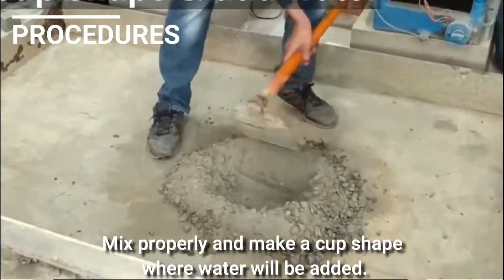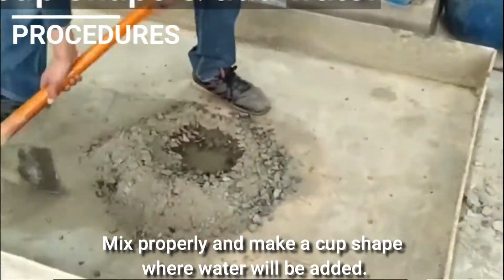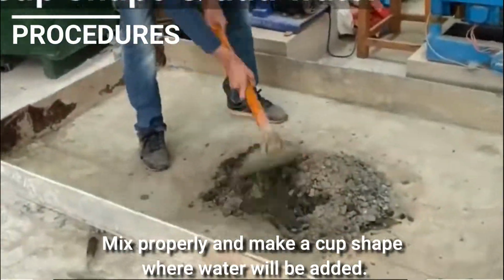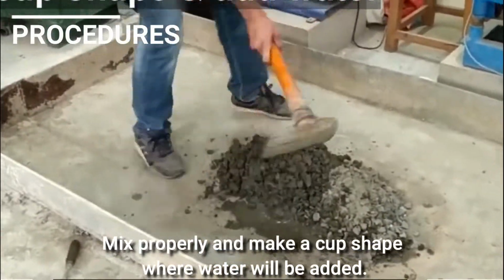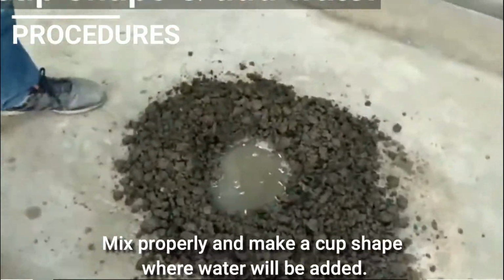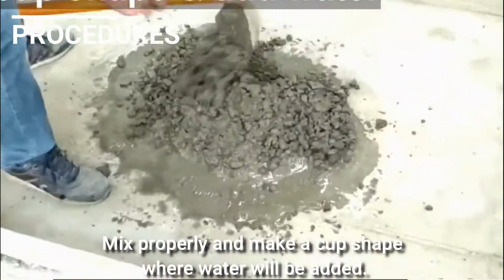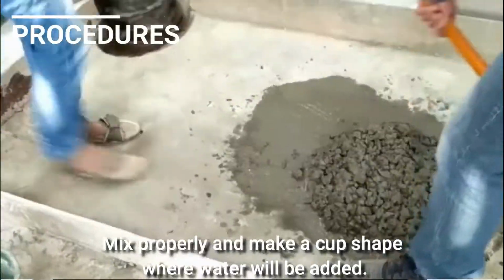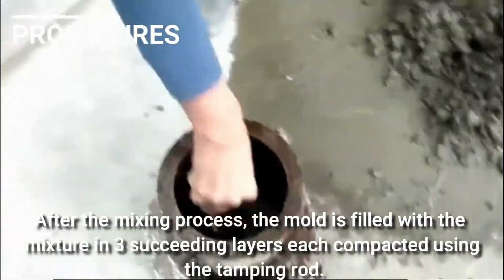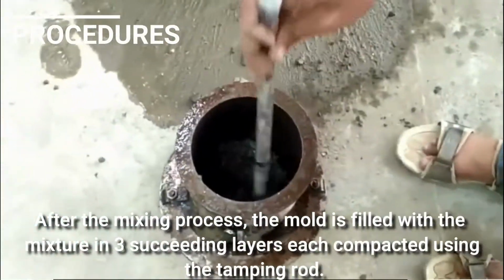Fourth is to make a cup shape where the water will be added. After the mixing process, the mold is filled with the mixture in 3 succeeding layers, each compacted using the tamping rod.